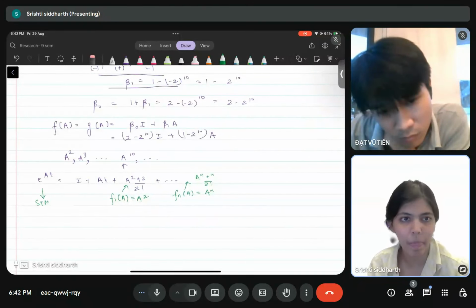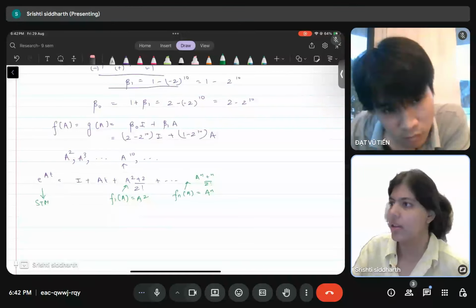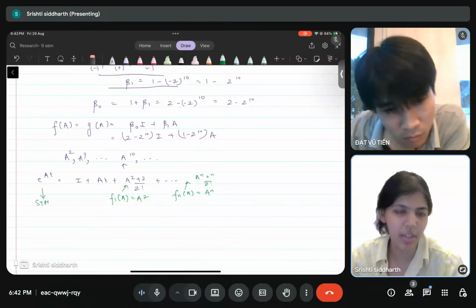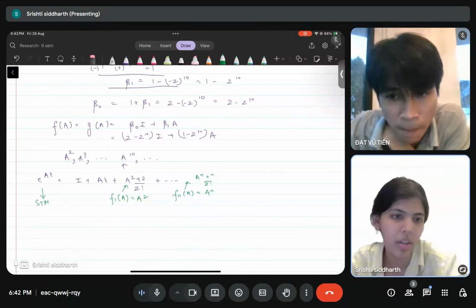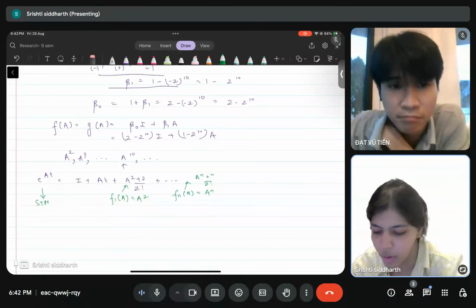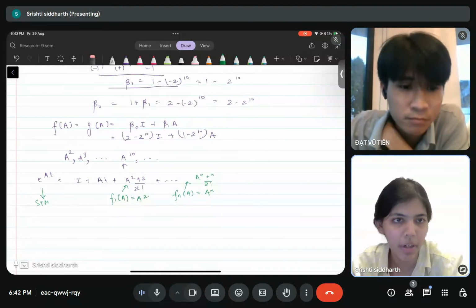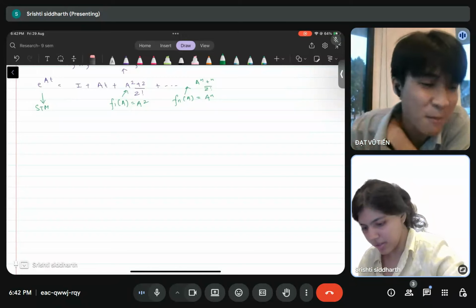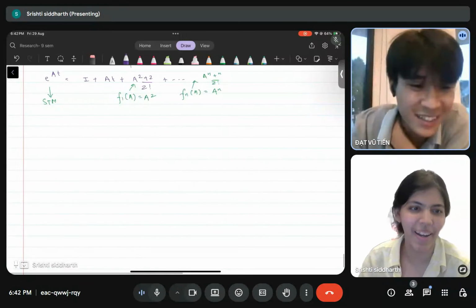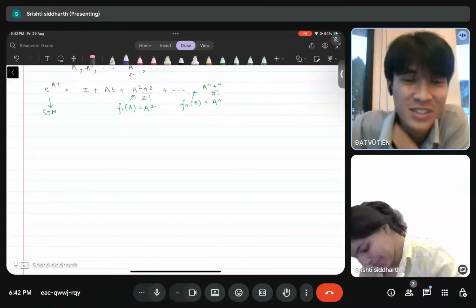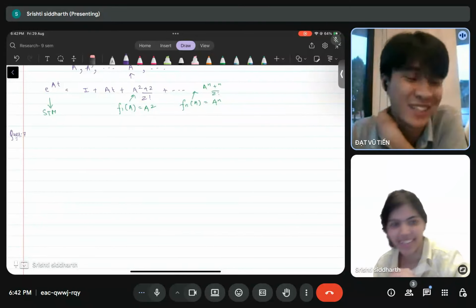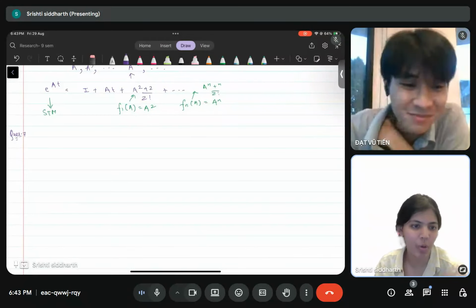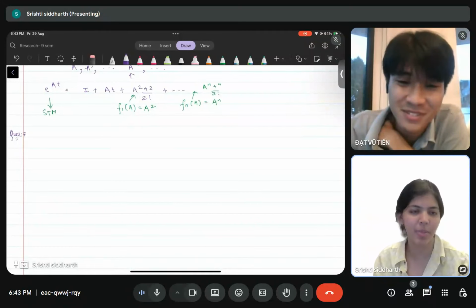state transition matrix. So we looked at, I think, three ways to compute the state transition matrix. One is the Laplace inverse. One is using diagonalization or conversion to Jordan normal form. And then the last one was to use the Cayley-Hamilton theorem. I think usually if we have a complex system, we'll just move on to MATLAB, but it's nice to look at some of the ways as well.